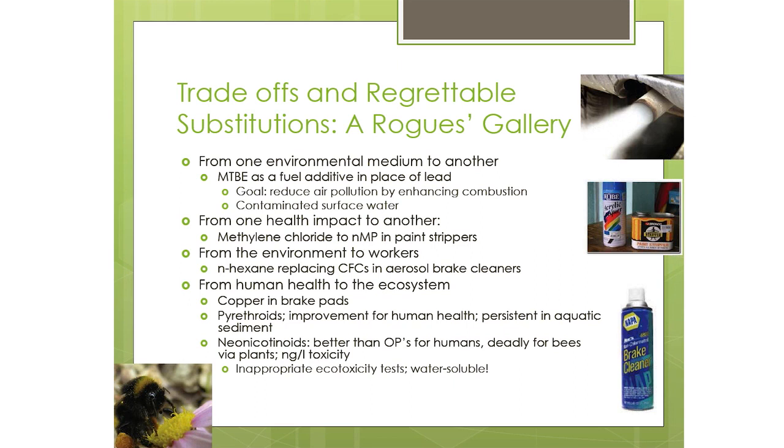The Montreal Protocol banned CFCs as a propellant, and one of the downstream effects was that we saw peripheral neuropathy in auto mechanics who were dealing with aerosol brake cleaners and breathing 7 or 8 cans of them a day, because, unbeknownst to the rest of the occupational health world, we'd replaced CFCs with n-hexane, which was actually known as an occupational hazard in other occupations, but not in this particular one.